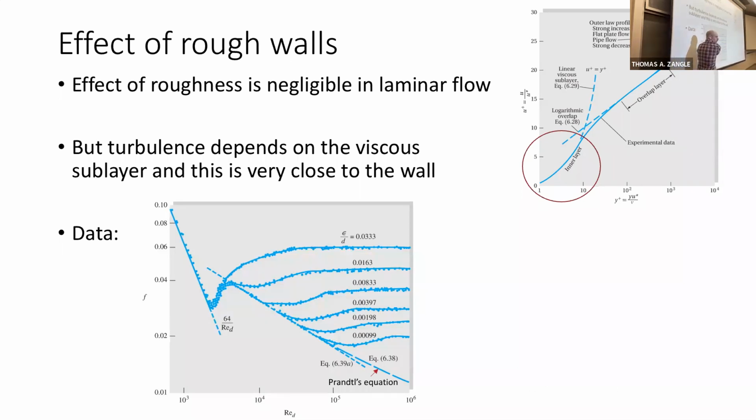We get into this region here. What is this region? What's going on in this region? Transition, right? This is the transition to turbulence. In this case, it's actually all pretty consistent. But you can certainly have this kind of jump from the laminar to the turbulent relation happening at multiple different points along here, which is what makes this region so hard to predict. Okay, but this is the transition region, and then we have this dashed line. That's the turbulent friction factor for the smooth pipe relation that we just developed on the previous slide.